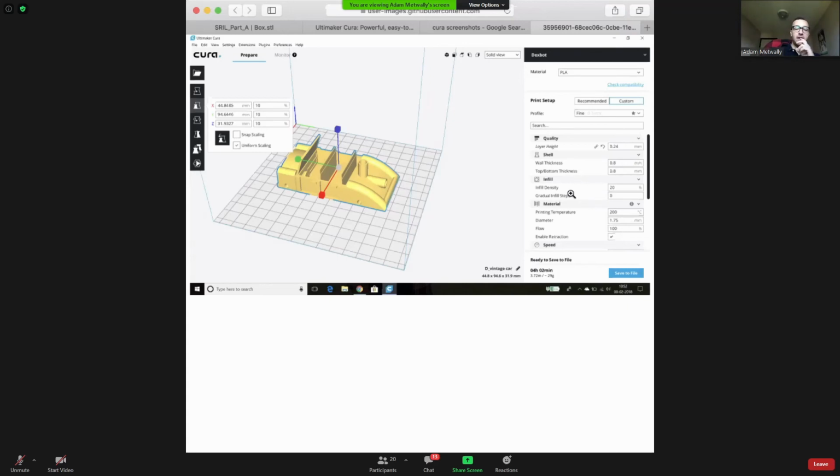Infill is another thing that you can check. When it's actually filling in the insides of the part, how much material is it using in there, whether that's 50% or 100%, and that will determine what it looks like on the inside, and how structurally rigid it is.